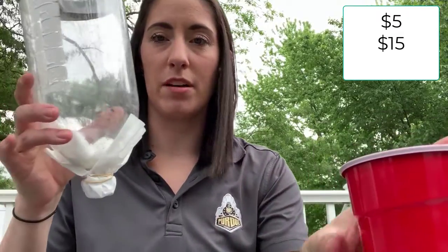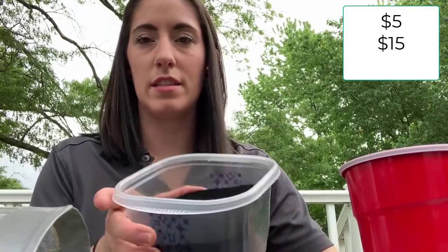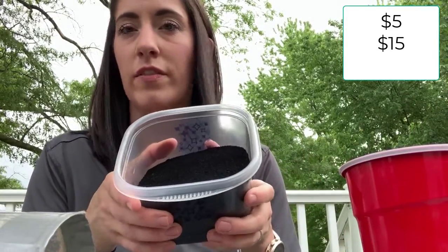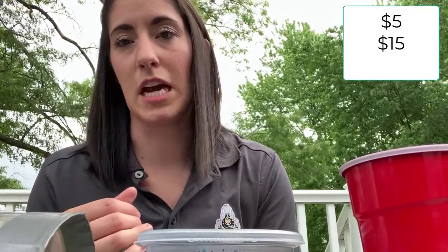Now that I've got my cotton balls in here, I think I'm going to throw in some activated carbon. So this is what activated carbon looks like. And if you've ever seen something like a Brita pitcher filter, it comes in that cartridge, or your refrigerator filter. They often have and are made with active carbon. So the way this works is this carbon has been burnt down.